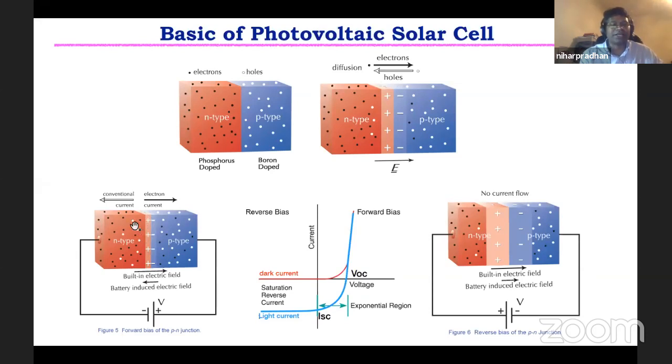All those electron and hole pairs generated by absorbing this photon, the electrons will move to one side and the holes will move to the other side. If we just connect a wire outside the terminals without applying any voltage, those free electrons and holes will flow through the outside circuit, and that will generate electricity. And this is the basic idea of the PN junction solar cell.